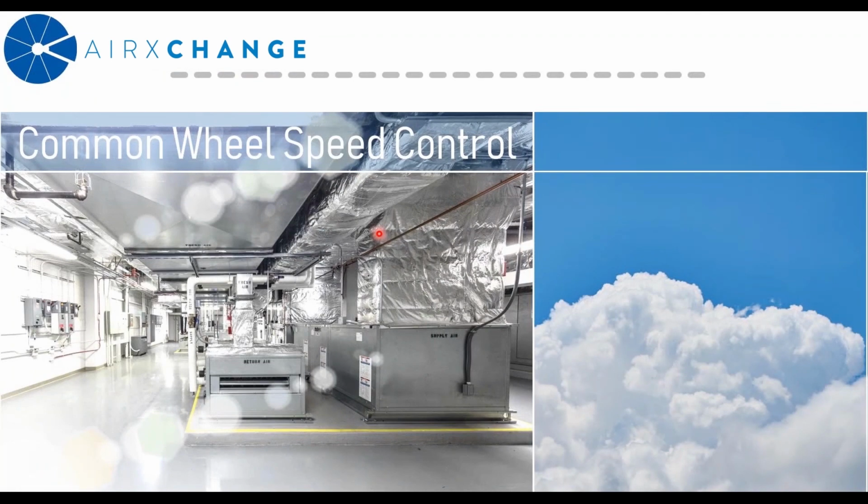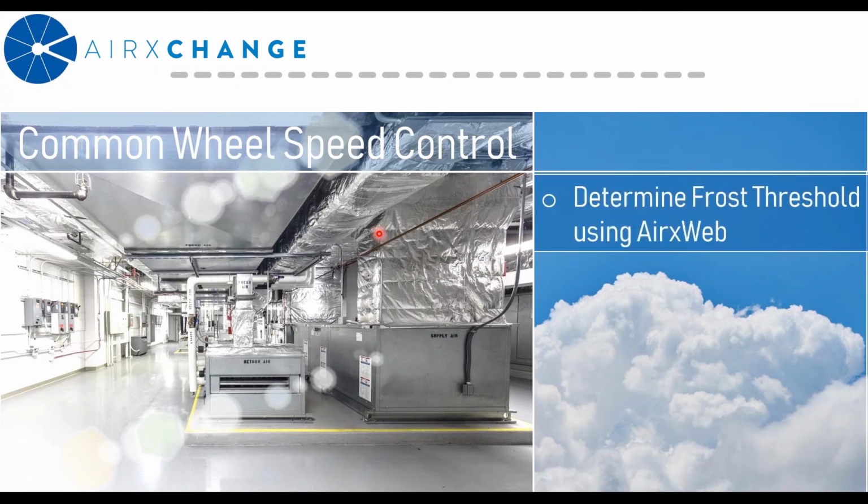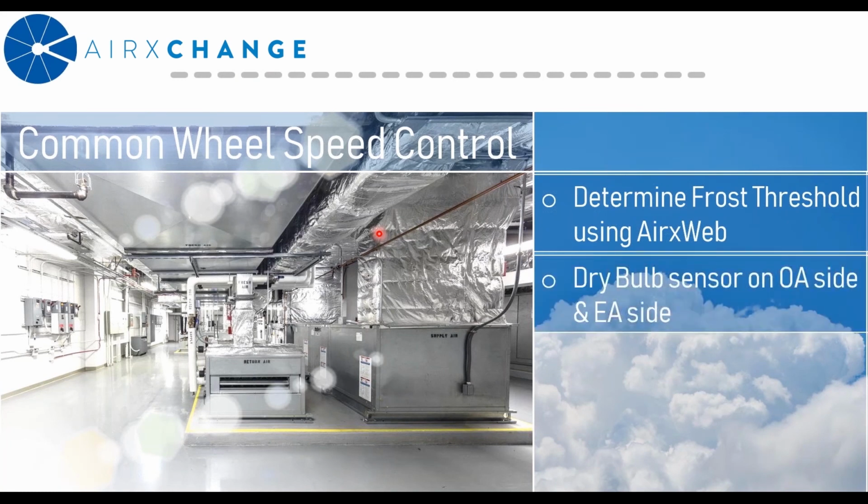So integrating wheel speed control into a system, once again, use the Airxchange software to determine if you have a frosting condition based on the operating conditions. If you do, there are two common ways to set up the system for wheel speed control. The first is a series of dry bulb sensors, one located in the incoming outside air to monitor whether the temperature is below the frosting threshold, and the other would be located in the leaving exhaust air to modulate the wheel speed to achieve a desired leaving air temperature.